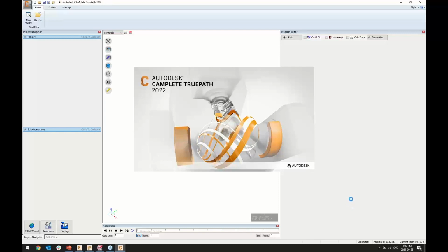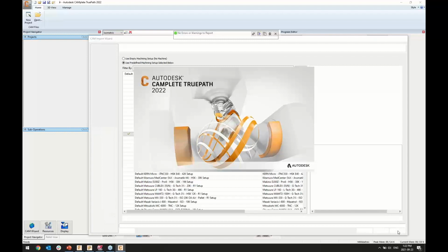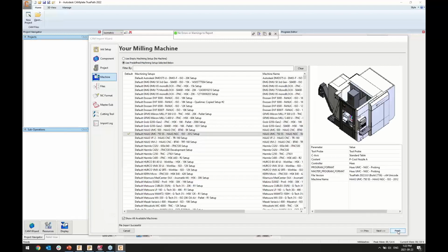The first step in that process, once all of this information is loaded, is defining what machine tool is going to run that particular project, because that machine tool will have a very particular set of instructions that it will need on the controller side, will have very specific travel limits, and just limitations as a whole that every machine tool will have. So the machine tool is really going to be the first element that we'll be selecting.